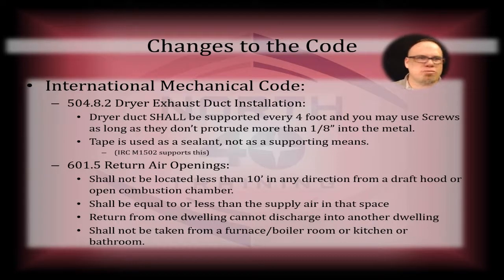And even though you might say to yourself, yeah, you know what, you're getting crazy now because we would zone that anyway. Of course you would zone that. No, if you zone it and it's a 100-degree day out or it's a 0-degree day out, there's a good chance both sides are going to call for heating or cooling at the same time. And if that's the case, you're going to be drawing return air from one space, mixing it together, and supplying it out into both spaces. Right? So there's no way to avoid drawing air from one space and putting it into another space in that type of scenario. So that would be a great example of where this portion of code would come into play.